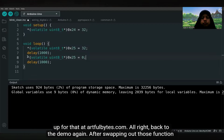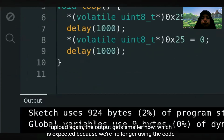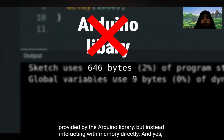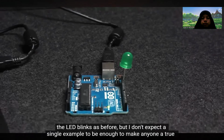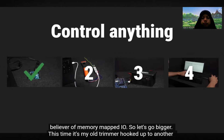Alright, back to the demo again. After swapping out those function calls with memory writes, if everything works as it should, the LED should blink as before, so let's upload again. The output gets smaller now, which is expected, because we're no longer using the code provided by the Arduino library, but instead interacting with the memory directly. And yes, the LED blinks as before, but I don't expect a single example to be enough to make anyone a true believer of memory mapped I/O.